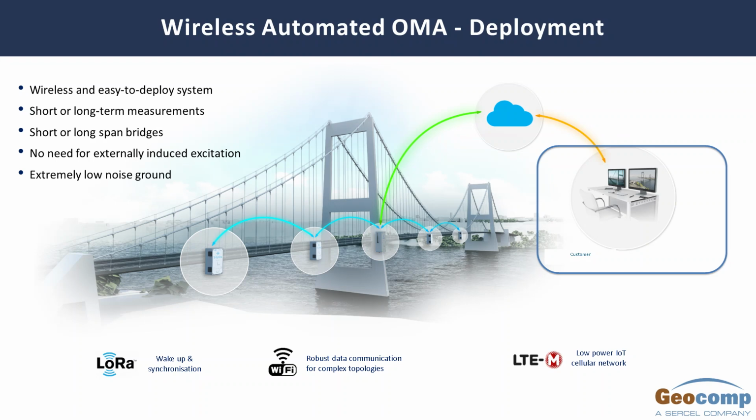So how can we do this in the field easily? At Geocomp, we have a very efficient way of doing that. We have wireless, super sensitive vibration measurement nodes. These nodes can be deployed on the bridge, whether it's long span or short span, with either a few feet between them or long distances between them. It depends on how densely you want to cover your structure and how much time you want to spend in the field. By just dropping them and taking 20-minute measurements, you will be able to see all these results easily.